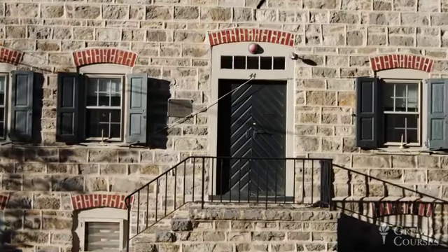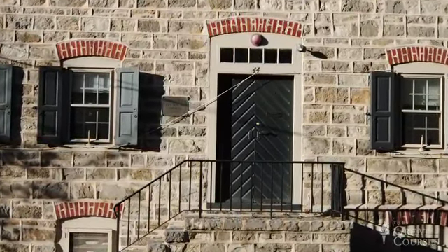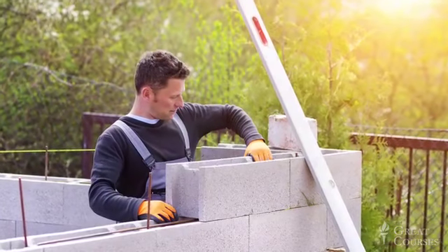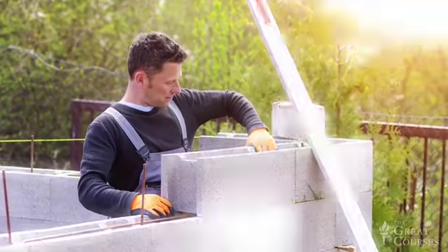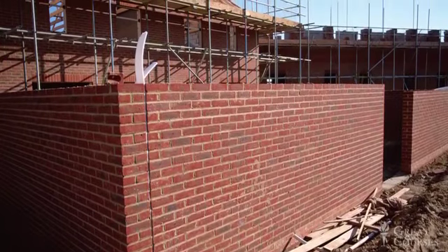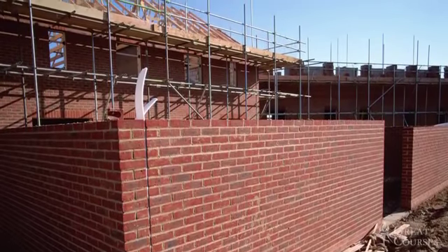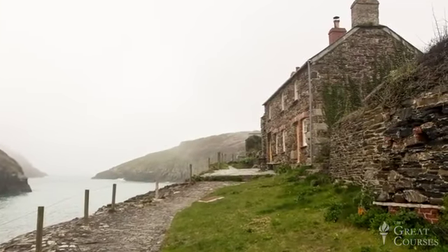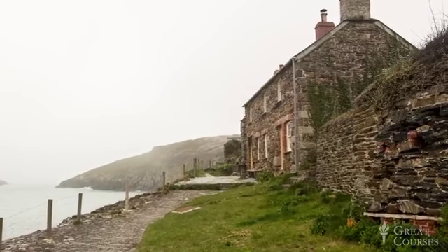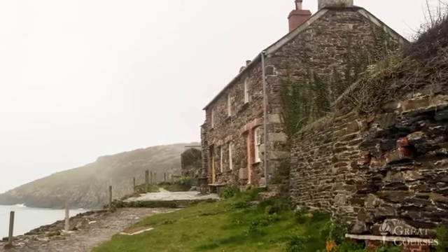The traditional bearing wall structural system is relatively more expensive than the other two types because those solid exterior walls generally require a lot of material, skilled labor, and time to construct. On the other hand, these buildings gain a certain efficiency from the exterior wall's ability to serve simultaneously as both structure and enclosure. And the resulting structure is both strong and fire resistant, characteristics that explain why so many centuries-old bearing wall buildings have survived and remain in beautiful condition today.